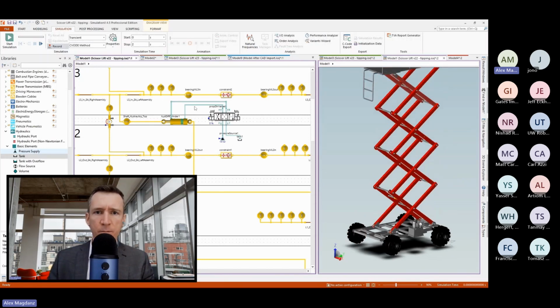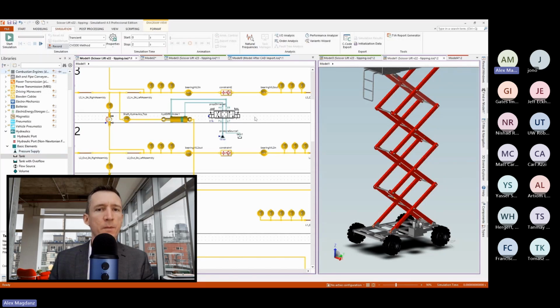So we've got a basic hydraulic system set up here. We have a 100 bar going in as the source, the tank's at atmospheric pressure. Now I'm going to copy in a signal for the proportional directional valve so that we can see something happening during the simulation. And this signal is quite simply going to be between -1 and 1 so that it just changes the position of the valve so that we can see something happening over time. And let's simulate that now after setting the stop time to 14 seconds.